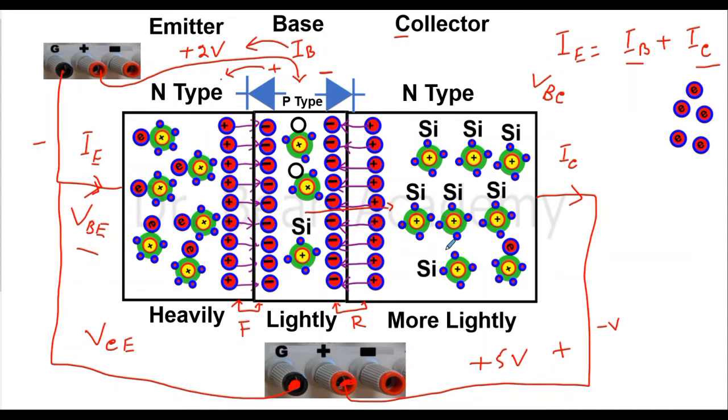So as I said before, the common emitter setup or configuration is used when we need a high current gain. As you saw, a huge number of electrons will go through the collector, so we will see a huge current at IC for a small current from the base. That current is IB.